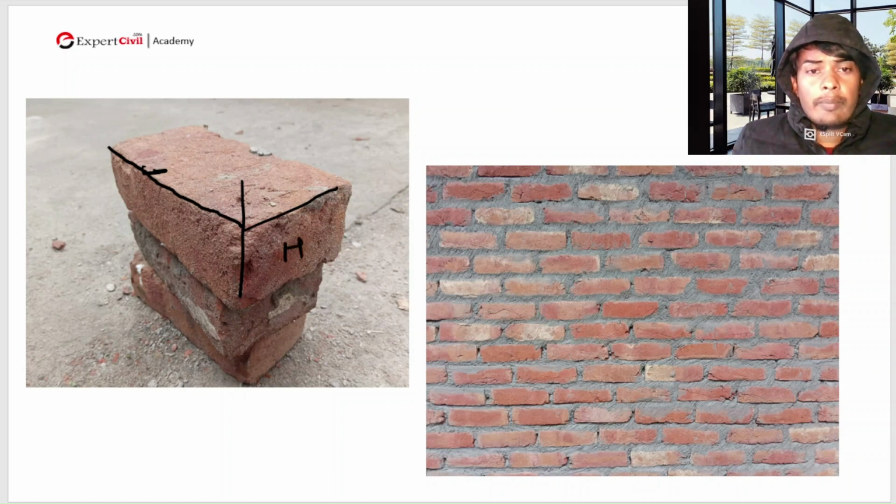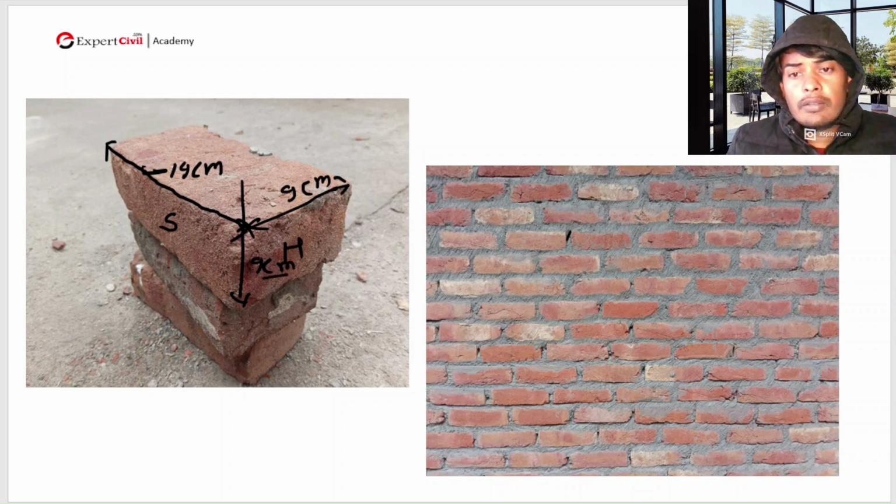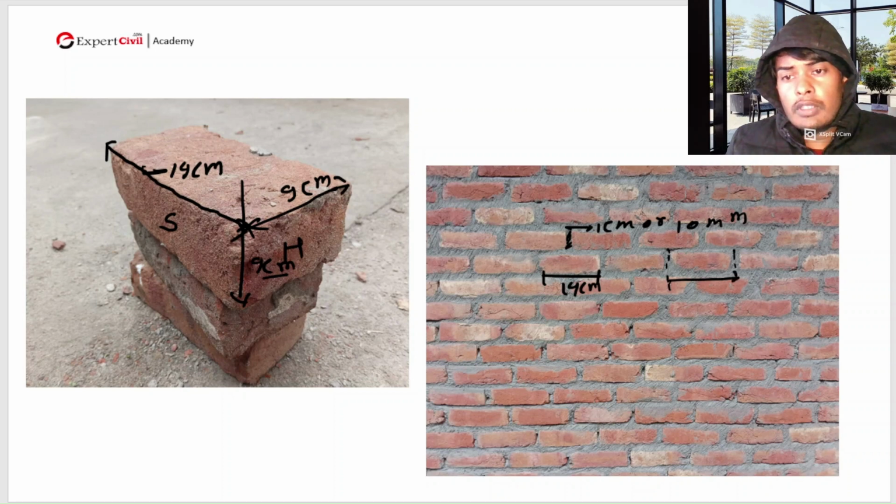Okay, this is the header, this is the stretcher, and this dimension is 19 centimeter and this is 9 centimeter and this is also 9 centimeter. Okay, now this thickness is 1 centimeter or 10 mm. Okay, so this is 19 centimeter and you can see this will become 20 centimeter.